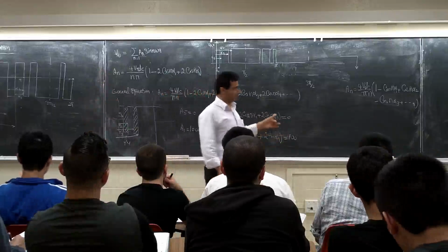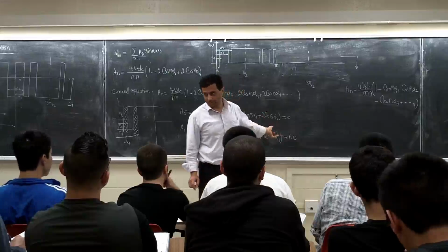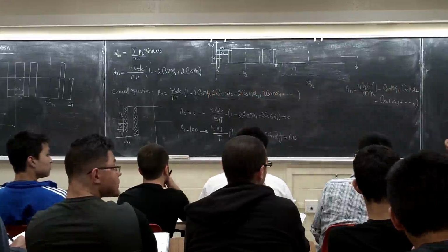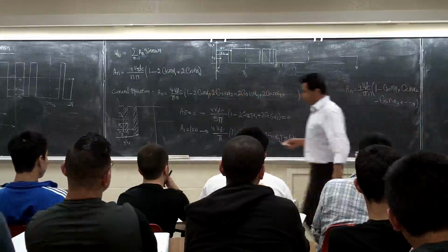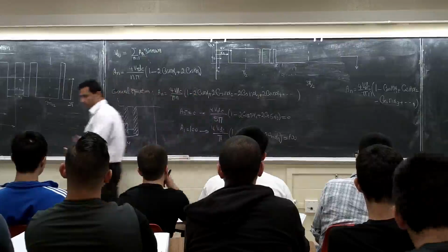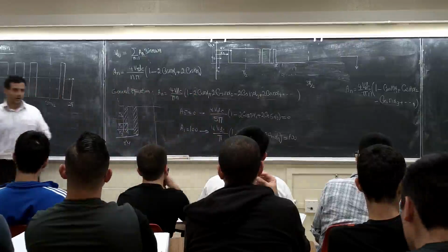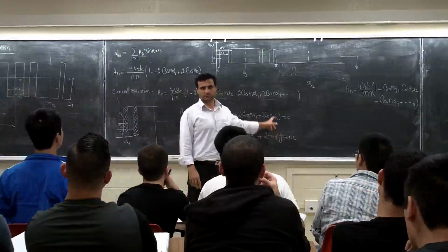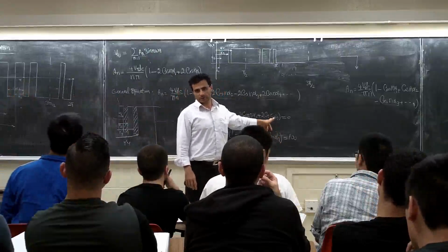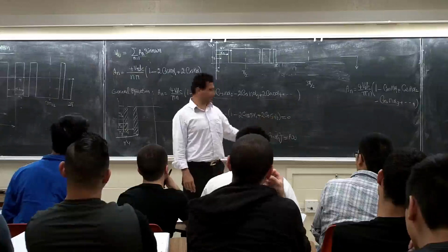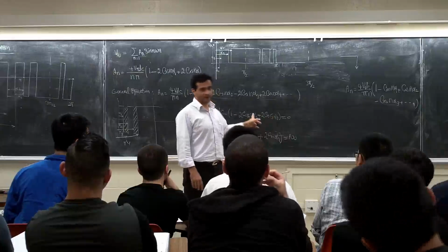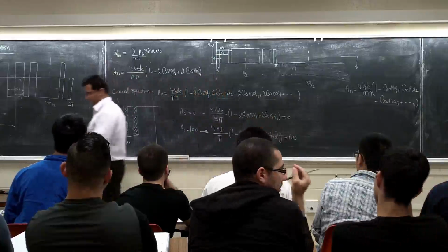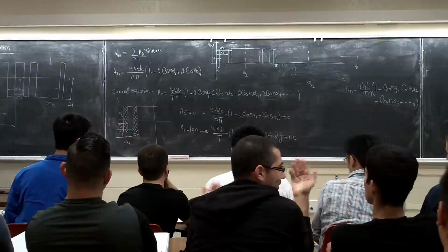If it's a single phase, you could have a third harmonic, but if it's a three phase, you don't have to be worried about the third harmonic. Understand? So that's the way to work with harmonics. I'll give you one problem in homework number 2. You can practice it a little bit at home, because this is a non-linear equation. You guys think that this is 5, this is the alpha 1, this is 5 alpha 1. It's not easy to solve it. It's going to take time to solve this equation.